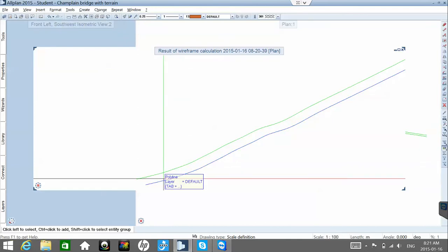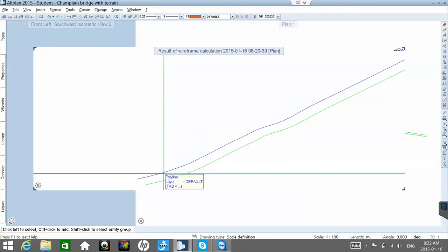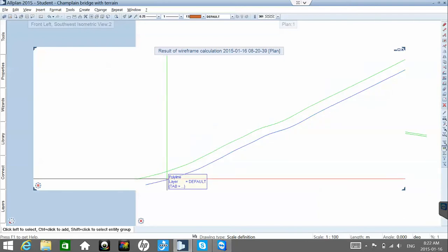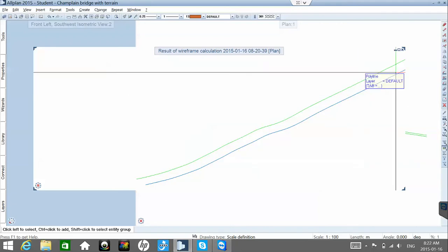Okay, you had the line, and if I select one line, it will ask me where it should continue. I just pick up the next red segment and it will convert all in one single polyline. And now you have two polylines because it's easy to do modifications. If you had an assembly of numerous lines, it would be more complicated. Okay, so now you have them.